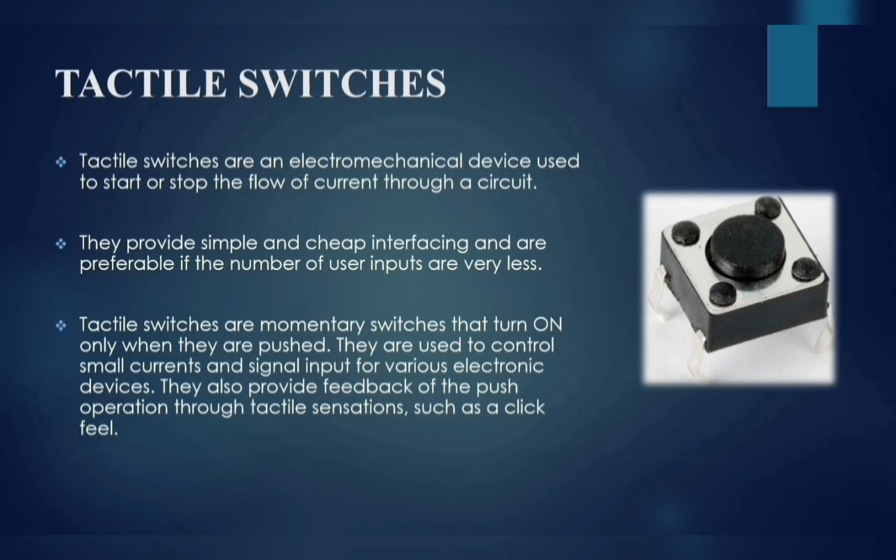Tactile switches are momentary switches that turn on when they are pushed. They are used to control small currents and signal input for various electronic devices. They also provide feedback of the push operation through tactile sensation, such as a click feel.